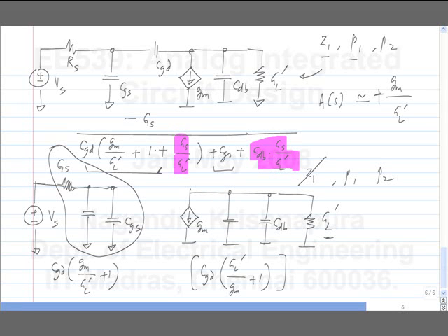This is quite useful for, let's say, a digital inverter, which is sort of broadband, and you have a small overlap capacitance between the two. In that case, you can divide it into some capacitance on the input side, some on the output side, and calculate the time constants. You will be more or less okay. Whereas in this case, when we consider CGD to be dominant, at the high frequency pole the gain has fallen off so much that it doesn't make any sense to calculate it.